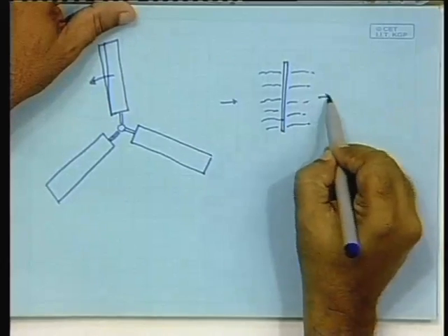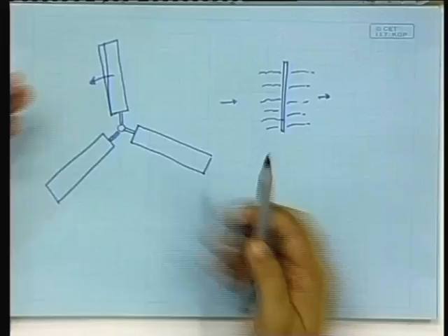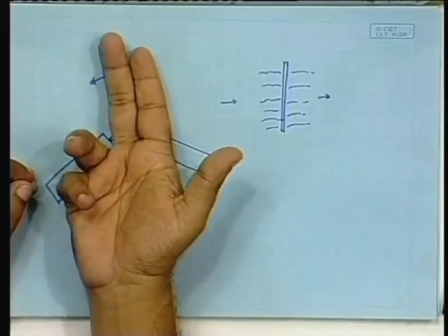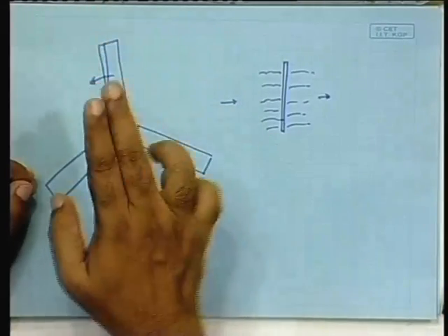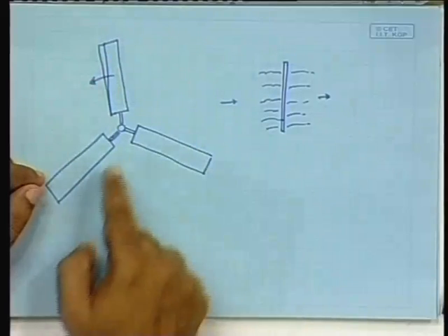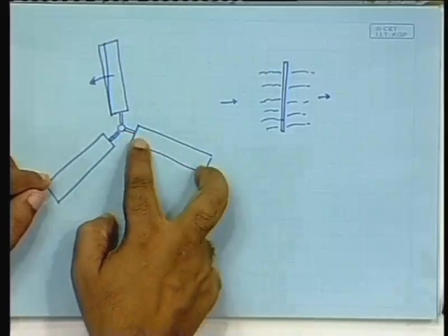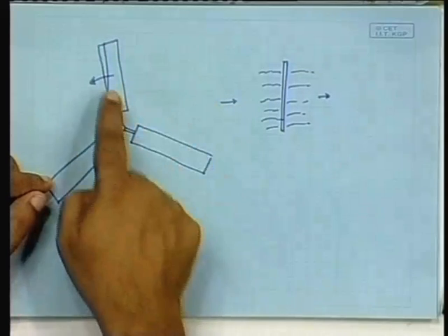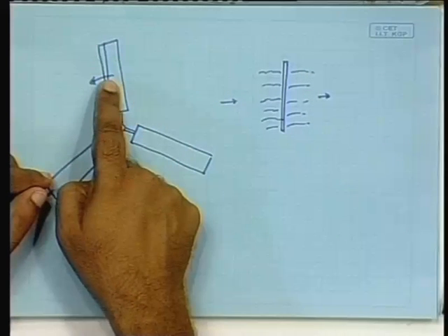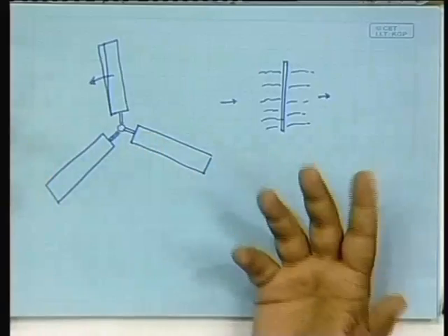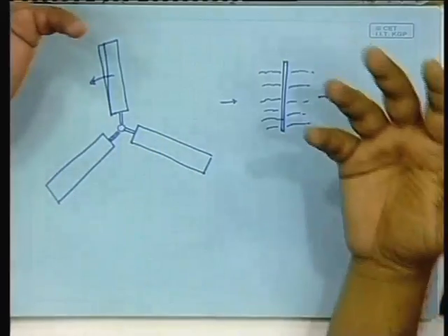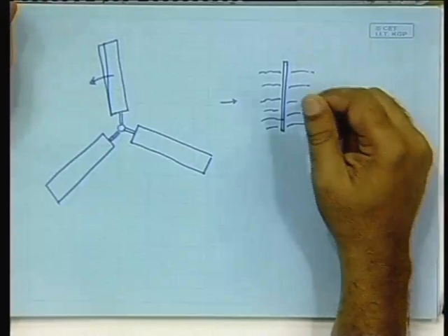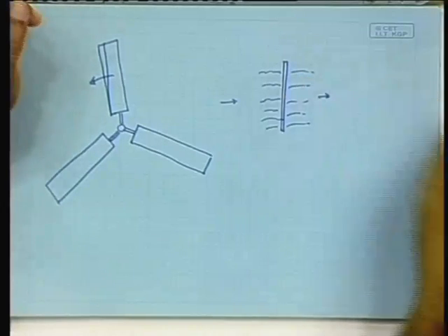So, the blade is rotating, and as a result it is disturbing the wind, both upwind as well as downwind. Now, if the next blade comes into the position taken up by this blade before the disturbance passes away, then obviously it will run into a disturbed wind. It will be seeing turbulent wind, and naturally the whole efficiency will go down.